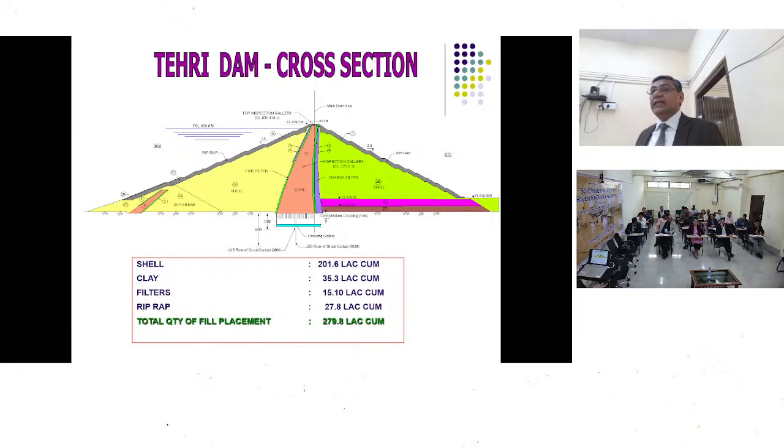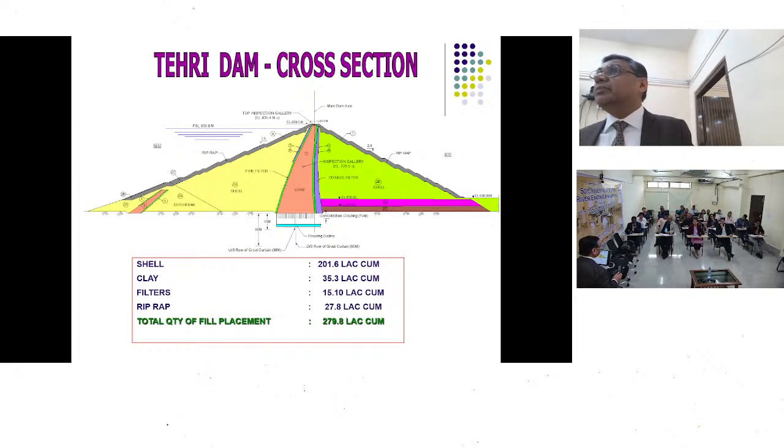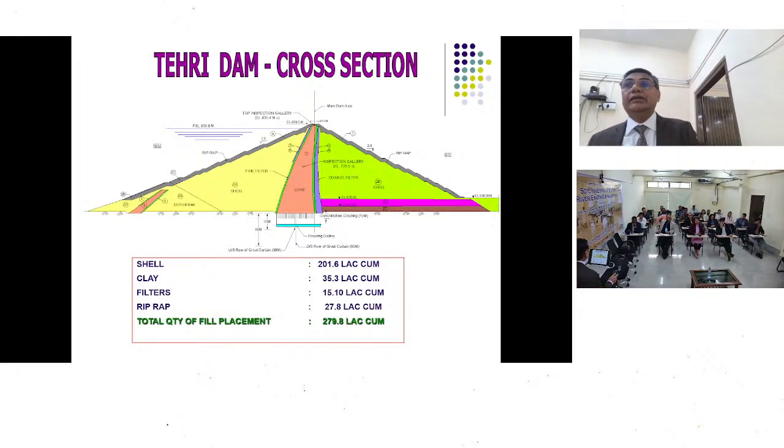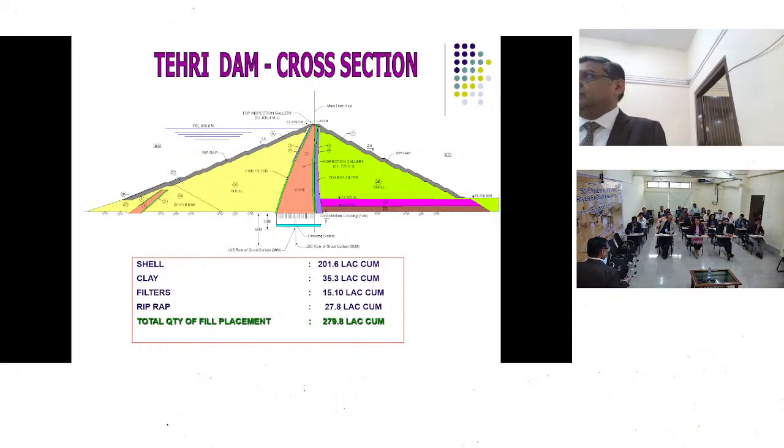Because as I was saying, this dam has been constructed in a region of high seismicity, that is 8.1 on the Richter scale, there was a possibility or thought that the shell material may liquefy. What is liquefaction? Liquefaction is a process in which under seismic loads the pore pressures get increased and the shear strength is reduced to zero. Okay, in simple terms.